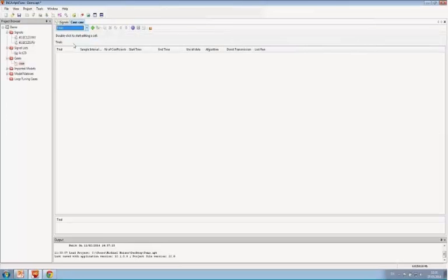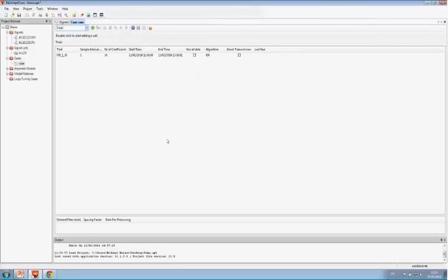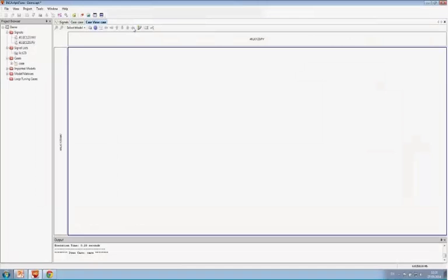Now I'm going to build a model, and I'm going to choose here to add a new trial, so building the model. I'm choosing 120 PID parameters, sampling time is 1 second, smoothing factor I leave to default, and I will only use a PID model for this example. Now we have added that, and as you can see, the case is showing up in red. That means that it has pending changes that have not been run yet, and I can run this case.